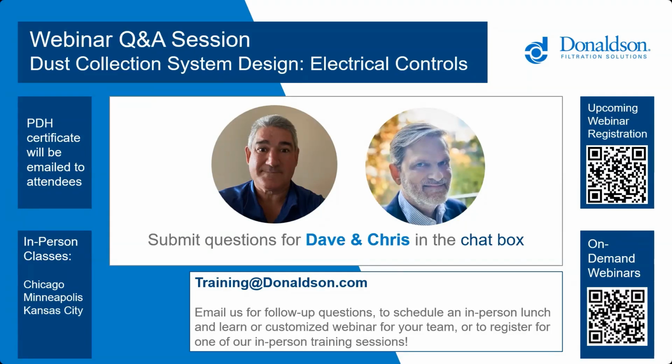Next question. I don't see explosion isolation devices being installed between your collector and the blower. Are Donaldson blowers rated for deflagration pressures that could be experienced in a deflagration event? I would say yes, and the ductwork between the fan and the collector is built to withstand that pressure also. Our fans are typically, on the smaller airflows, direct mounted to the collector. The collector construction is to a certain KST value, and the fan is built to that similar KST value. So it shouldn't be a weak point in the system if there would be an explosion there.